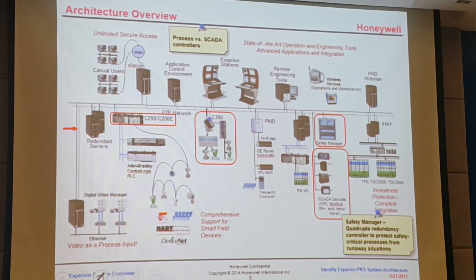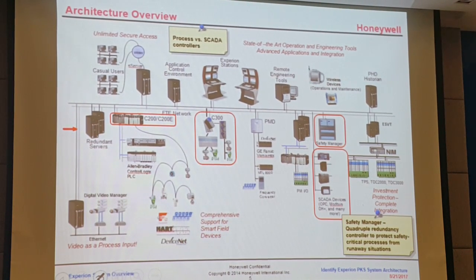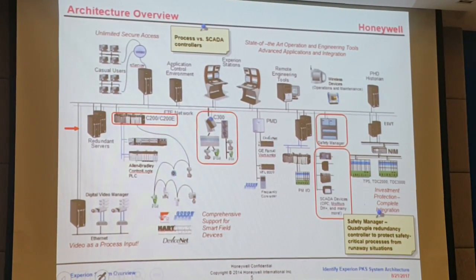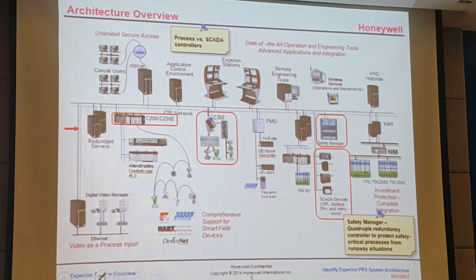If we take a look at the C200, one of the benefits of that controller is it has many different families of I/O modules. There is a 64 I/O unit limit. If you stay within that limit, you can mix and match the different families into the same controller.